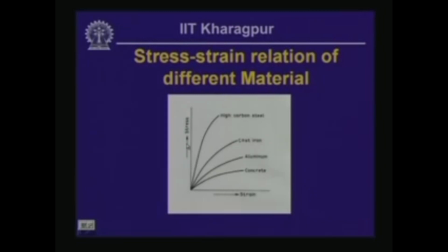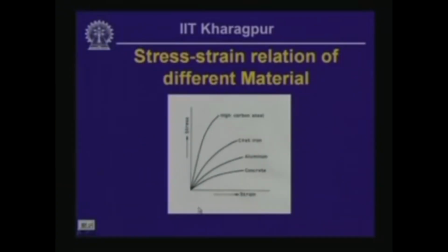In strength of materials, when we deal with stresses within the elastic limit, we need to know the value of the yield stress beyond which the member will start yielding. So, we try to limit our stress when we deal with the elastic level of analysis. We like to limit our stress up to the elastic level. So, we need to know the value of the yield stress, but from this kind of stress strain distribution, it is difficult to know the value of the yield stress.